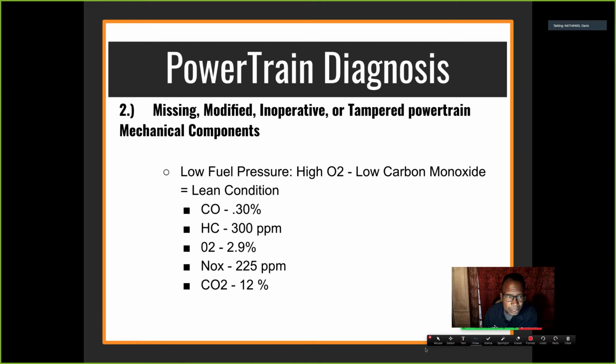Well, it can be, because you could have a bad spark plug wire. You can actually have a bad spark plug wire, especially in computerized cars, right? And the oxygen does not burn, and it goes past the O2 sensor. Once it goes past the O2 sensor, the O2 sensor does not read unburned gas. It reads oxygen. So it's going to command for more fuel.